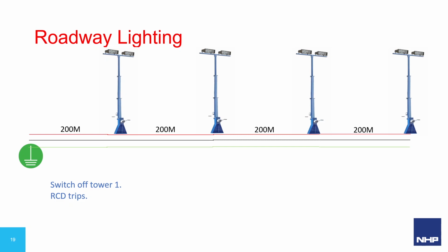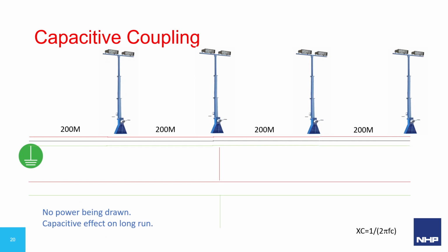So, to help explain this, in this slide, I'm going to introduce a capacitor symbol to the conundrum. In reality, any conductors of different potential running parallel to each other have some sort of capacitive potential, just like the plates of a capacitor. The greater the surface areas exposed to one another, the greater the capacitance and the lower the capacitive reactance.